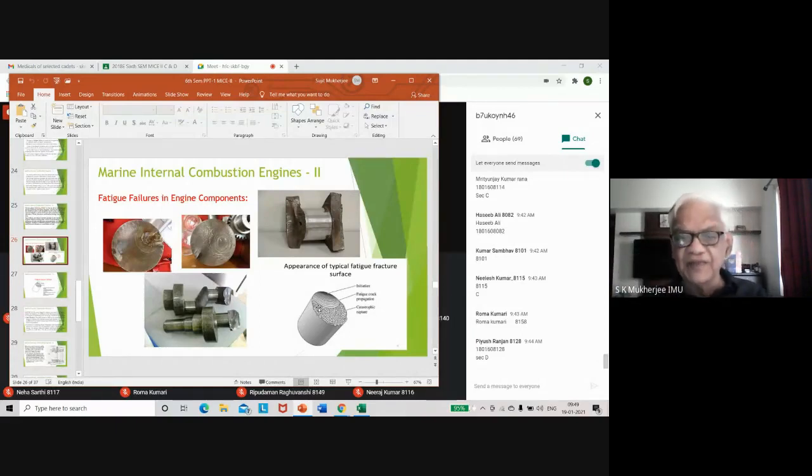Then there will be some stage where the strength of the rod is not enough to resist the torque that is being applied. So the remaining part of the shaft will break suddenly, and that breakage will give a surface which is very rough in nature and shiny in nature. Because when you look at it, you see spangles, the steel spangles which are fresh, exposed to atmosphere.